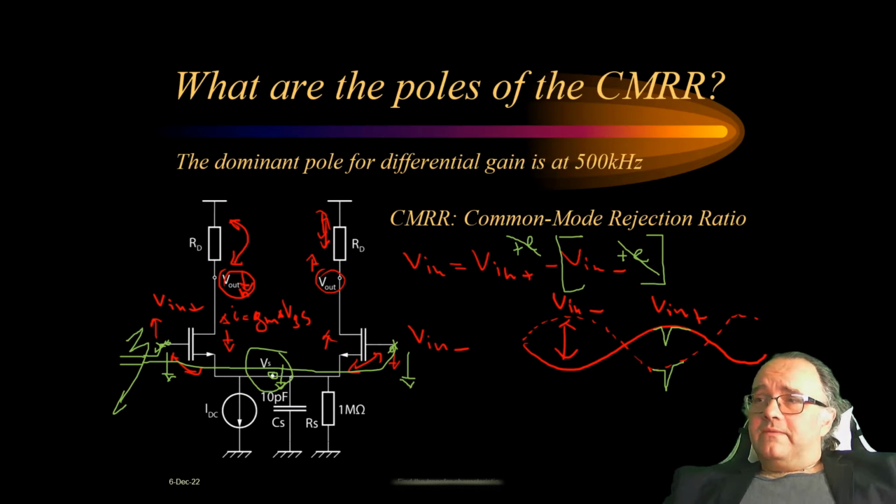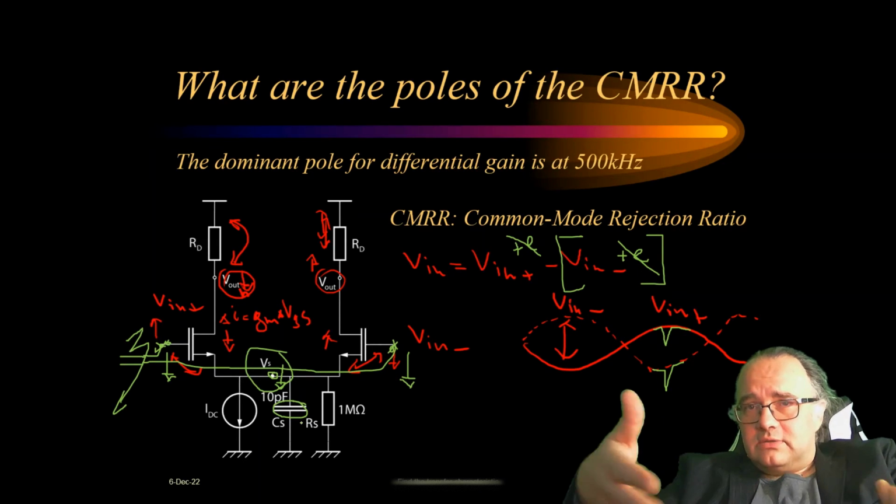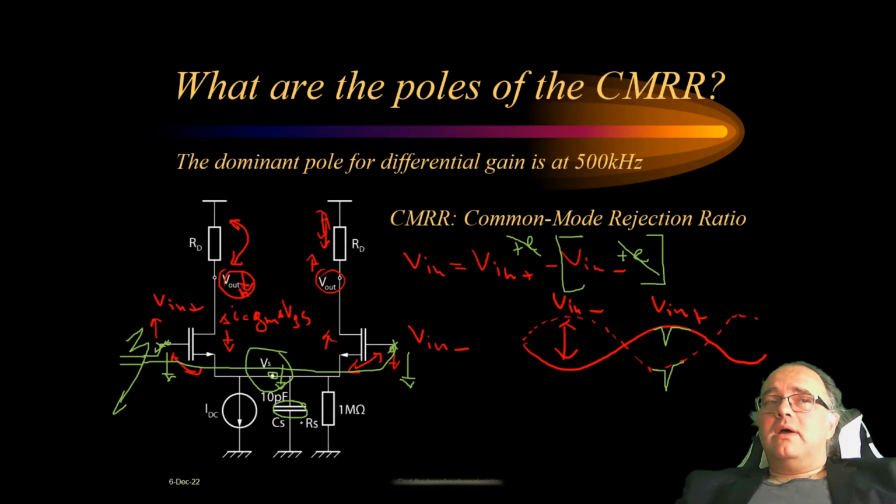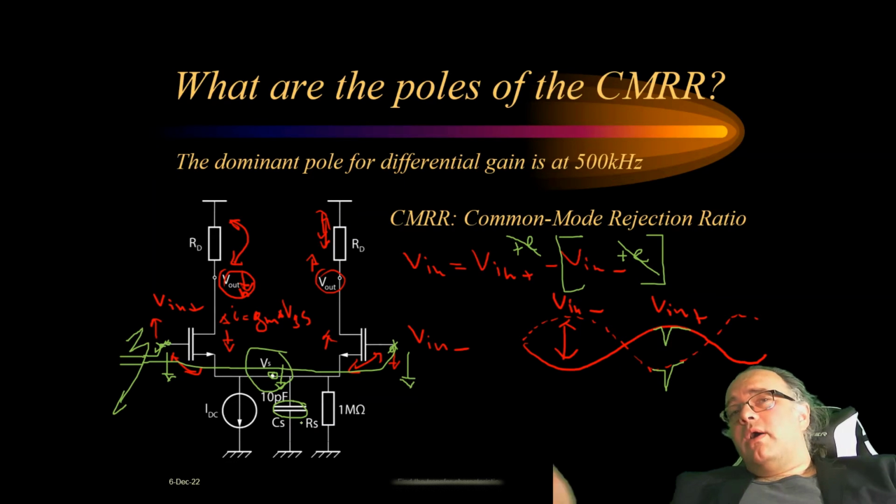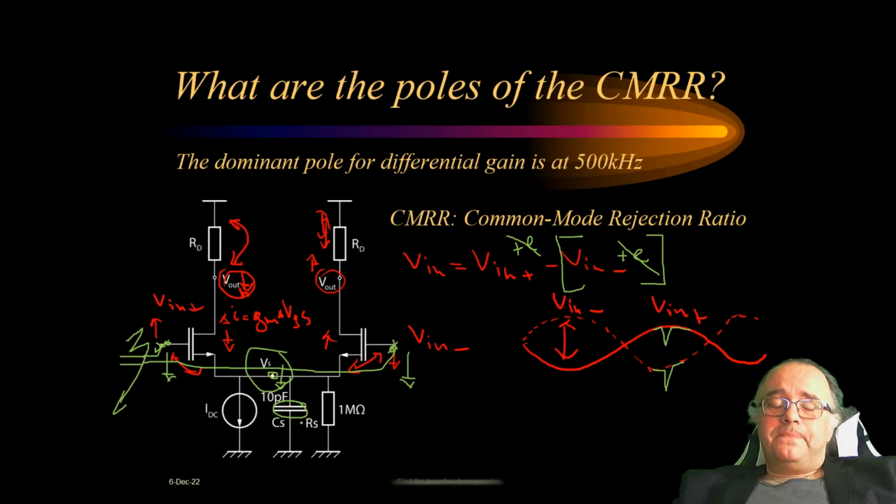If we have a change in voltage in a certain node, then we require some charging or discharging of this capacitance. If there is charging or discharging of the capacitance of a node, there will be a time constant, because these charges should come and go out through a time constant. This means that this will create a pole.